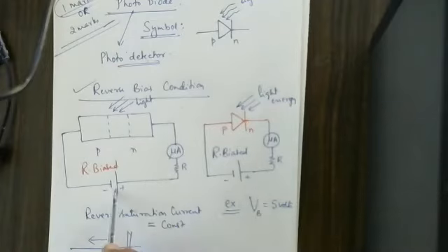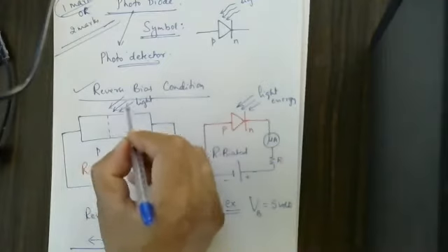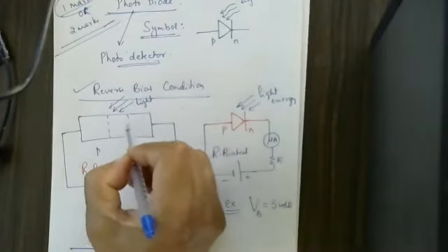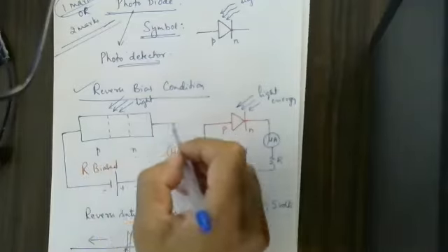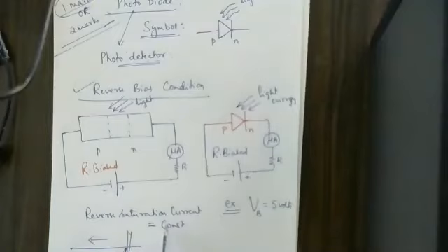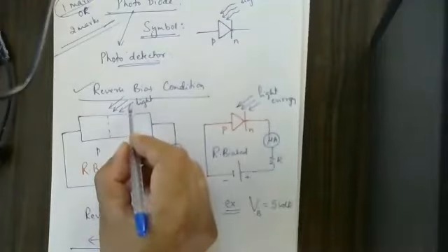Okay, the voltage supply is kept slightly lesser than the breakdown voltage. Then if light energy of a suitable wavelength is incident here, covalent bonds break up, and the number of hole and electron pairs increases here. Hence the current strength suddenly increases because of the light energy.